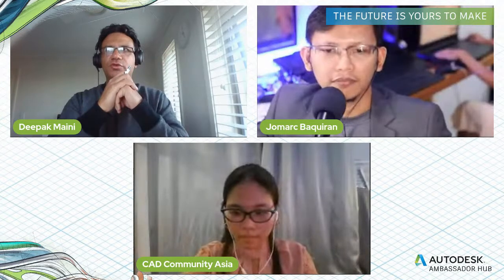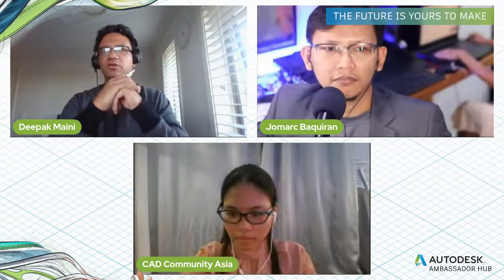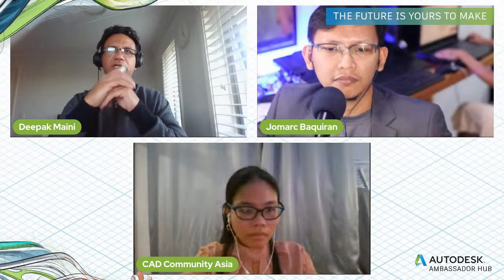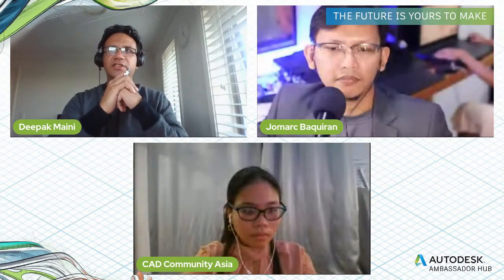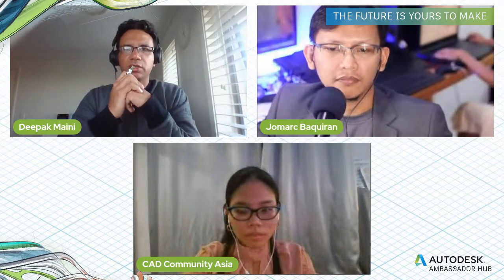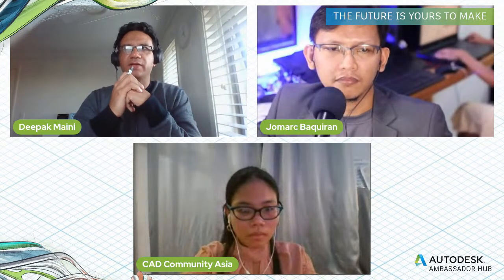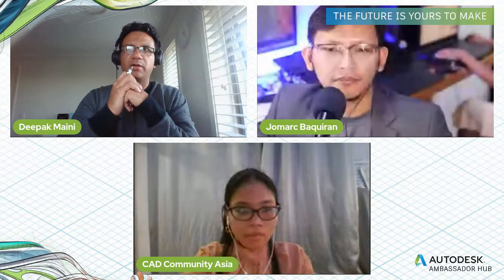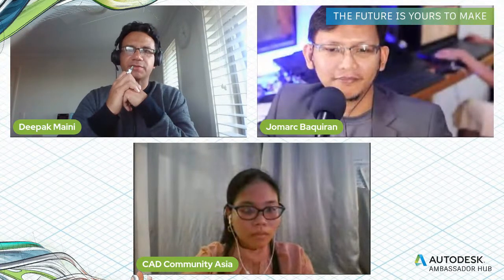Normally it is the architects, or it'll be the contractor. It depends. In most cases, we have seen it's the architect that takes the responsibility of setting up the project. So the project would be set up on their account, and various services and disciplines can bring their own BIM Collaborate Pro license and work in a collaborative environment. The role would either be BIM managers or BIM coordinators.